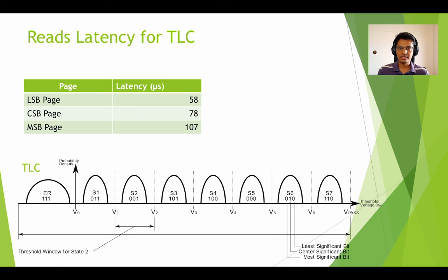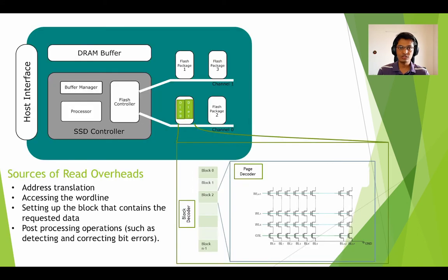Ideally, one would expect the latency to read an LSB page to be 4 times lesser than that of an MSB page and 2 times lesser for a CSB page. However, this is not observed in practice due to overheads involved in the read operation.